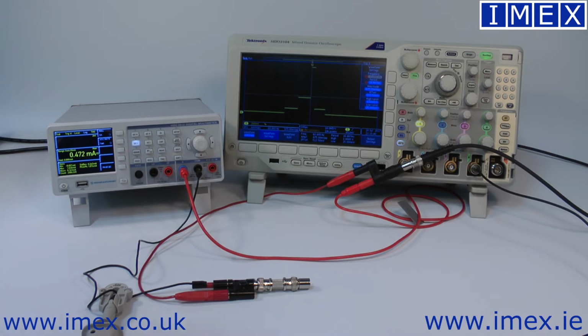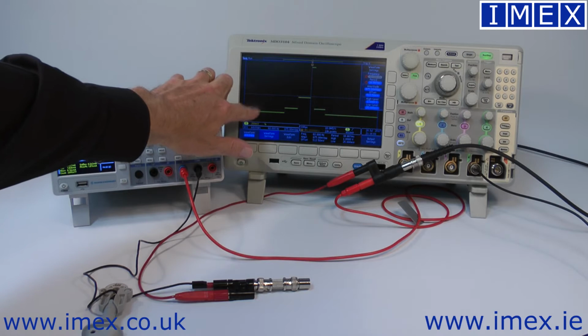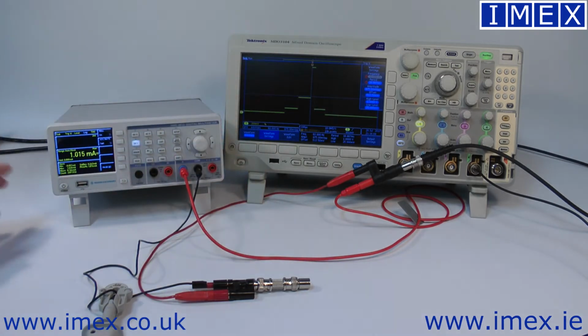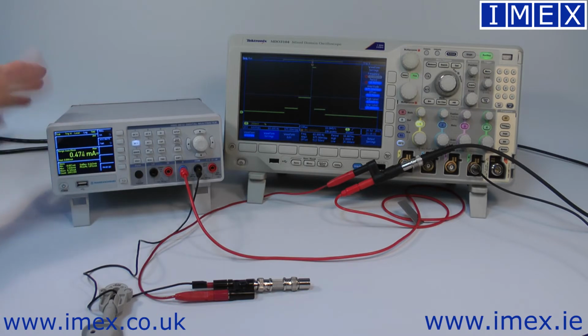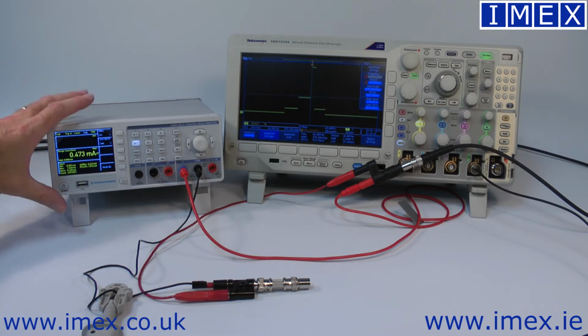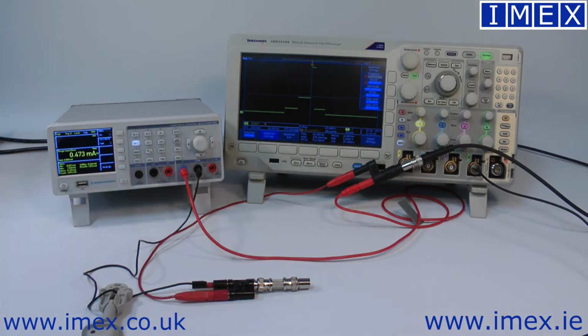So if we want to make a simple current measurement, get our mean current to see how long our battery is going to last, I can put it on a simple DMM like this. That's showing approximately half a milliamp as its kind of ballpark reading. That would correspond to our low level sleep current, but on the maximum it's showing 1 milliamp, and that's simply because a standard conventional bench DMM, regardless of who it's from, this one's Rohde & Schwarz, it could be a Tektronix, Pico, anyone at all, a normal DMM is not designed to measure fast signals like this.